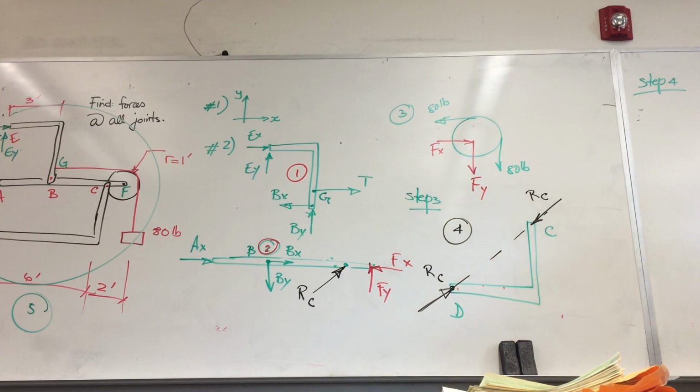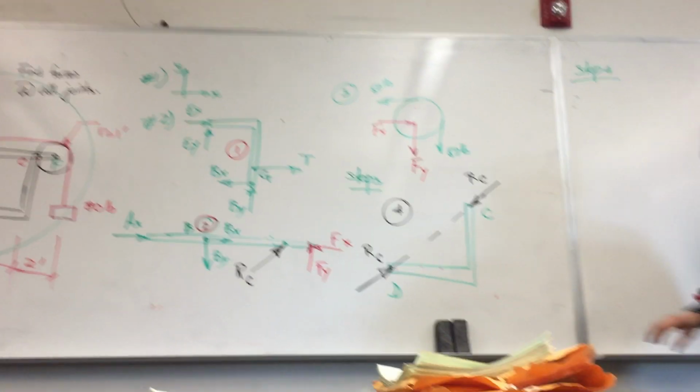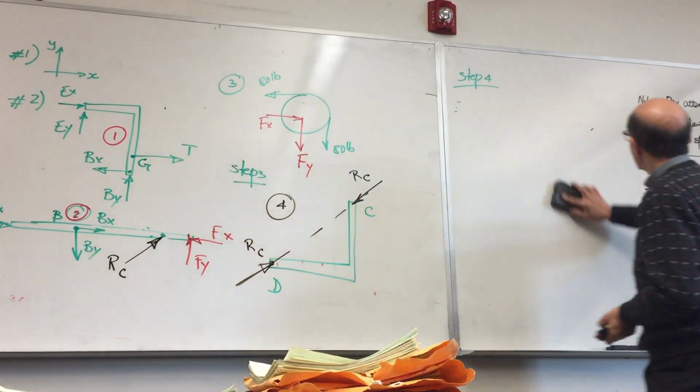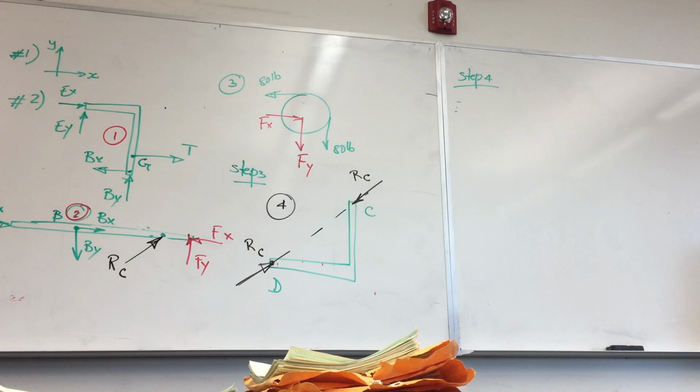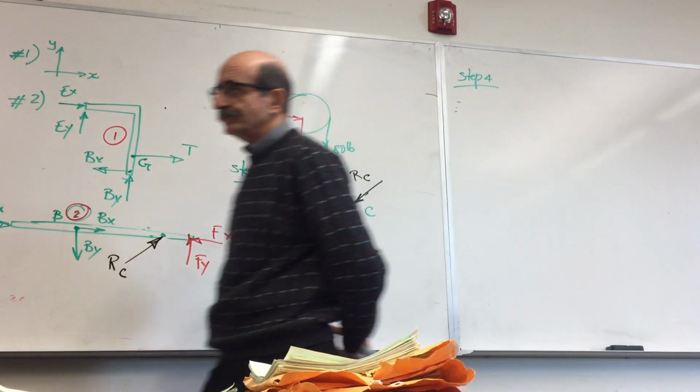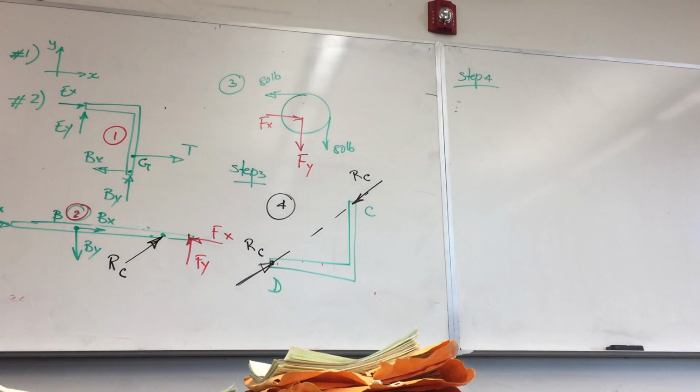Number 4, right? The only thing that you will find out is anytime you have a 2-force member, obviously that member has the least number of unknowns, but then you discover that you already applied all the equations of equilibrium. So by using that free body diagram, you cannot find anything, because there is no load acting on that member. You just have one unknown and 0 equations, because you've already used equations of equilibrium. Okay? Yes? At D, is there a reason you made it R?